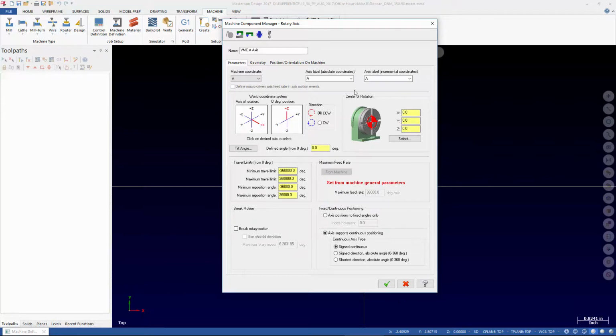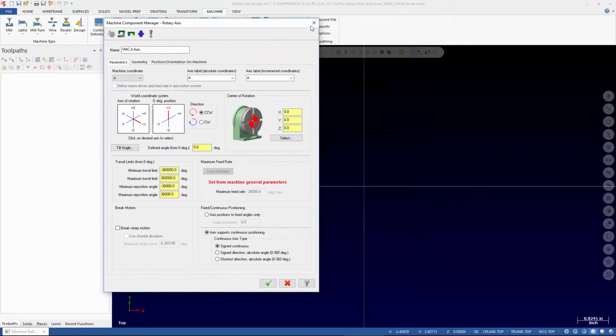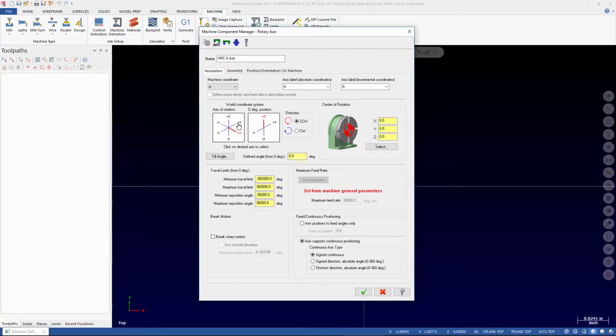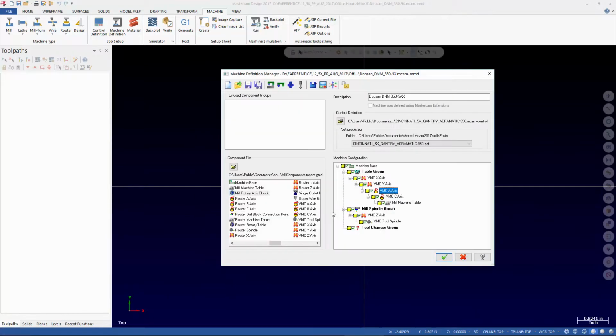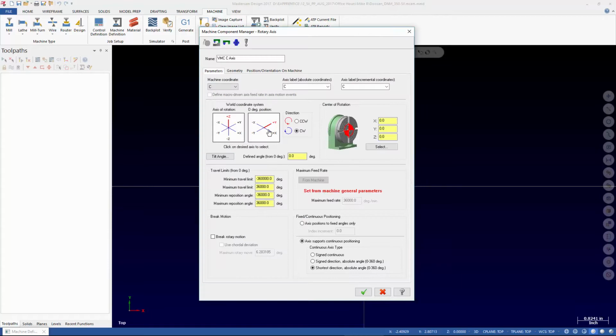say for example that we just wanted to rotate something so that our tool was pointing to the side. All we want is A-axis motion. If we go into the C-axis, in order for that to be true, the 0 degree position has to be located on X or Y. If we locate our 0 degree position on X plus, that means that whenever we rotate, we're going to have to get C-axis motion because of the way that the vector lies.